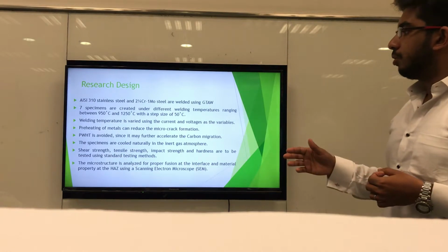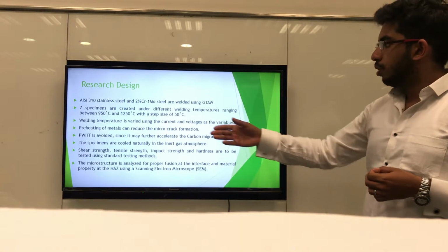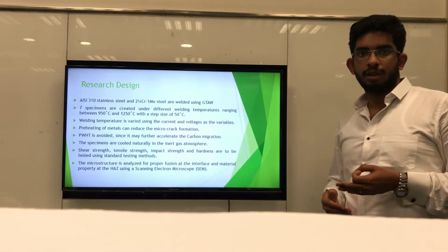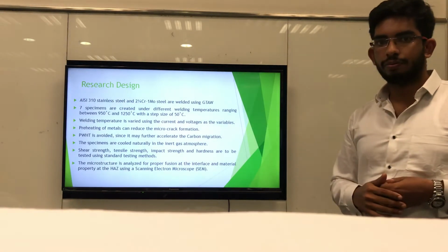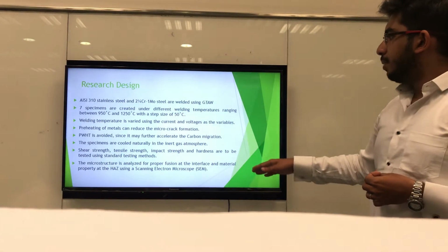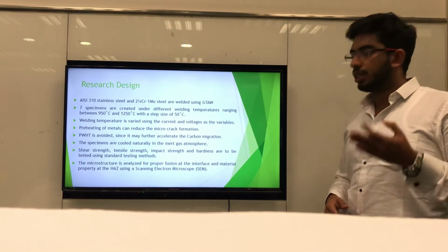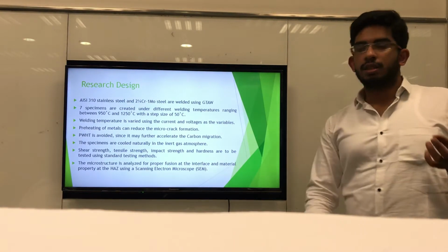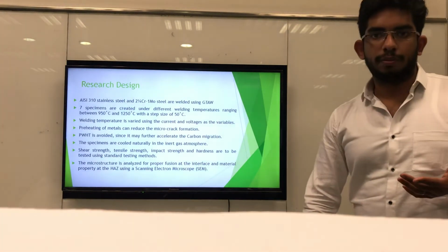Then it is subjected to mechanical testing for shear strength, tensile strength, impact strength, and finally hardness using the standard methods. For proper fusion and material property analysis, we are subjecting them to a microstructure analysis using a scanning electron microscope.